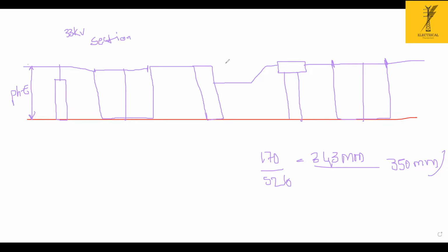Suppose let's assume the maintenance activities come up on the breaker. A person takes a ladder, climbs to this platform, and is doing work on this breaker. When he is working on the breaker, what condition are we checking? This person should not be exposed to the nearby live part. Nearby live part could be the next phase or the same phase.